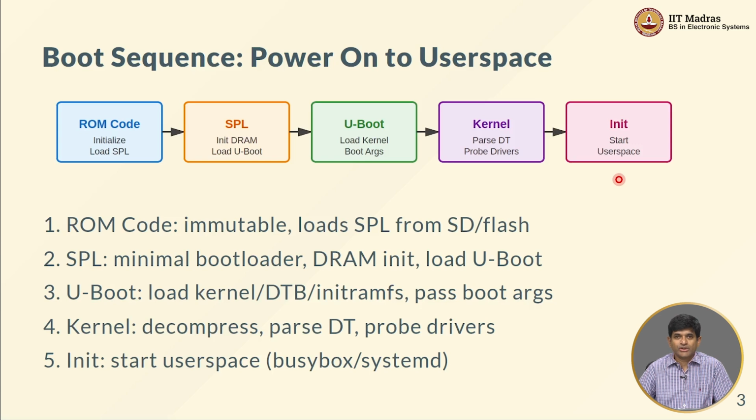So what is done usually is we take this power on, in fact there is something called the power on reset, right, and that signal is responsible for bringing one particular register inside the CPU to a known value. Well, it probably initializes most of the registers inside the CPU, but one of them is important. The most important one is what's called the program counter, right.